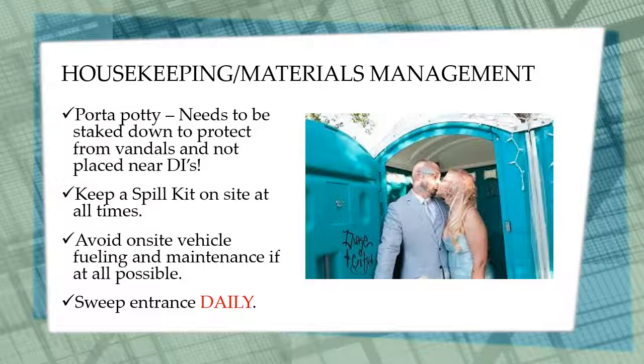Encourage the contractor to avoid fueling and maintaining vehicles on site if at all possible. Also remind them that they need to sweep their construction entrance daily to make sure that track out is not an issue.